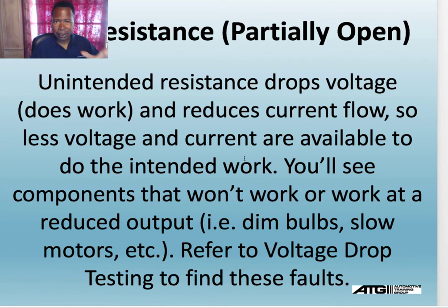Like a light bulb might be dim. A starter motor may move slower or not turn at all. A fuel pump may start the car up, but the fuel volume is so low that I have a high speed hesitation. Example: dim lights, slow motors. Refer to voltage drop testing. We already talked about it, right?